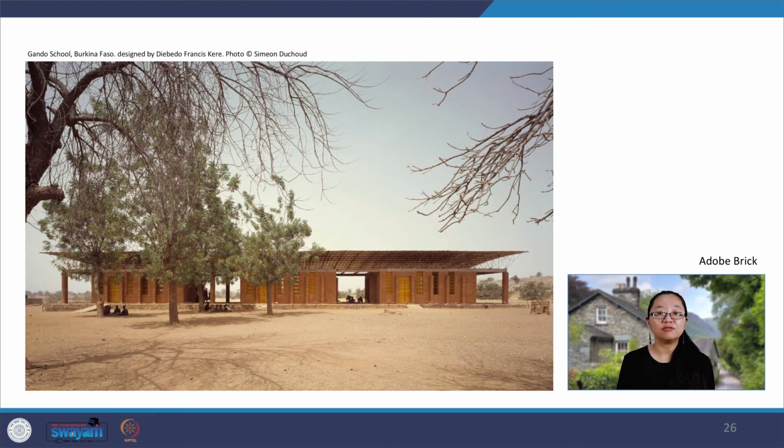availability, and construction feasibility. Clay is abundantly available in the region and traditionally used in house building, so a clay and cement hybrid was used to create structurally robust brick. These are not only easy to produce but also provide thermal protection against the climate. Despite their durability, however, the walls must be protected from damaging rains by overhanging roofs.